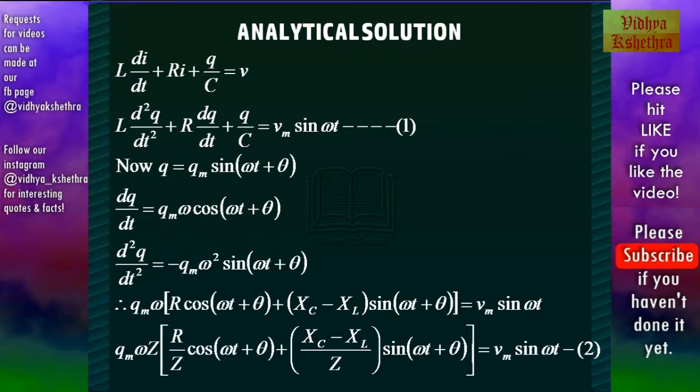Now, we know that q is equal to qm sin(omega t plus theta), where theta is the phase difference. Therefore, dq/dt is equal to qm omega cos(omega t plus theta). And d square q by dt square is equal to negative qm omega square sin(omega t plus theta). On substituting these values in 1, we get qm omega into [R cos(omega t plus theta) plus (XC minus XL) sin(omega t plus theta)] is equal to Vm sin omega t.